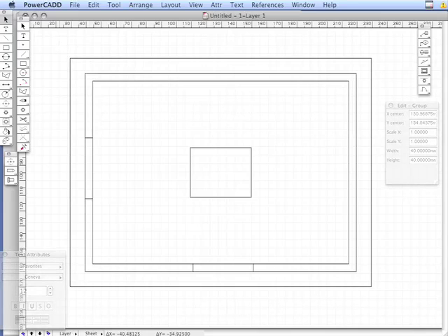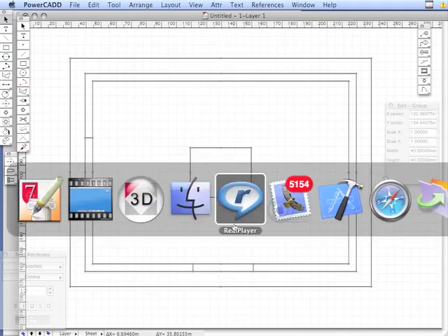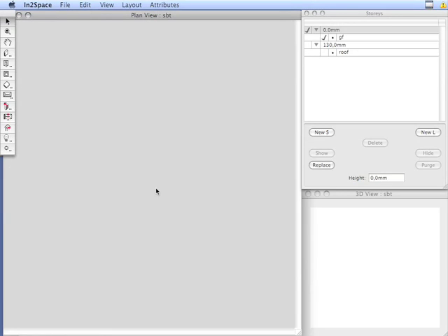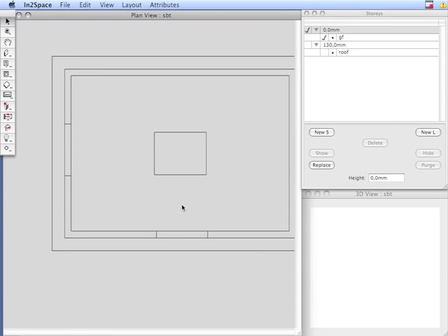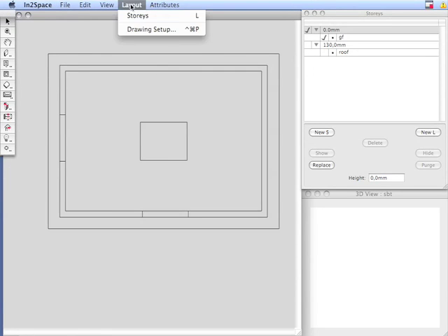It's a very simple thing, but it does show some of the features of PowerCAD and the interaction with Interspace very nicely. So let's go. Here's Susan's bird table. First of all, we cut and paste our profile into Interspace. Fit that to screen and set our drawing to 1:1, which is what the bird table was drawn in PowerCAD. Everything we do now will be matched exactly to anything we paste from PowerCAD.